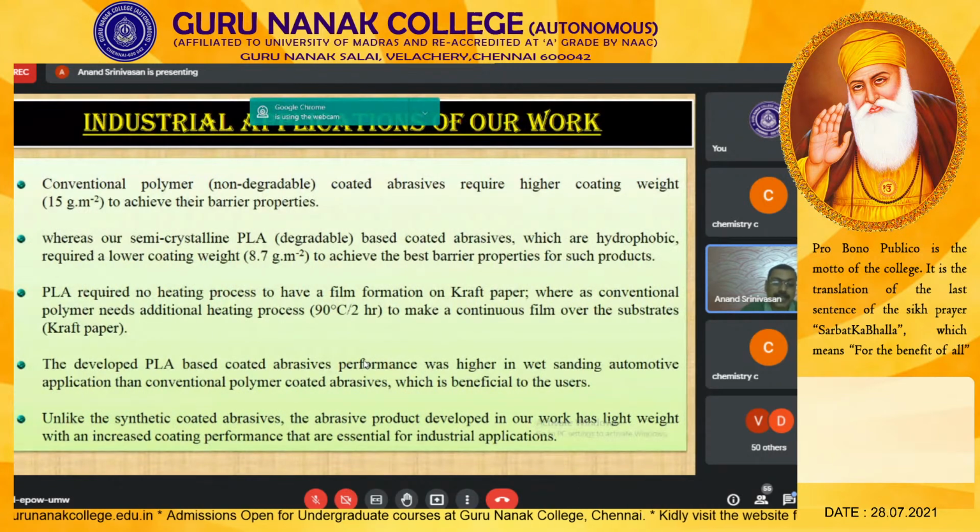Okay. Then the additional coating heating process, which is also meant for your conventional backing material. In this case, we are avoiding two heatings. In our case, only one heating is required, unlike the conventional process, where you have to have two different heatings. That can be avoided as far as our PLA is concerned.